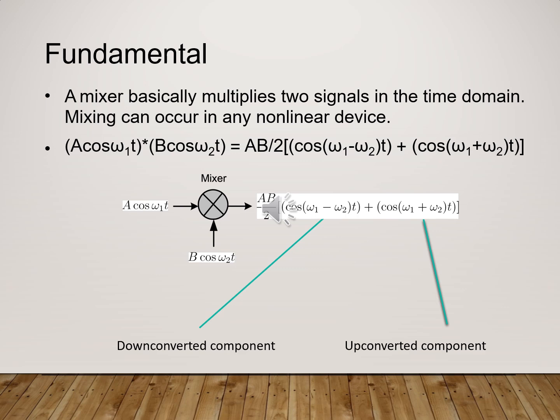How does an RF mixer circuit work? An RF mixer is a three-port passive or active device that can modulate or demodulate a signal. The purpose is to change the frequency of the electromagnetic signal while hopefully preserving every other characteristic, such as the phase and amplitude of the initial signal. Now, a mixer basically multiplies two signals in the time domain in order to transfer the incoming frequency to the intermediate frequency.